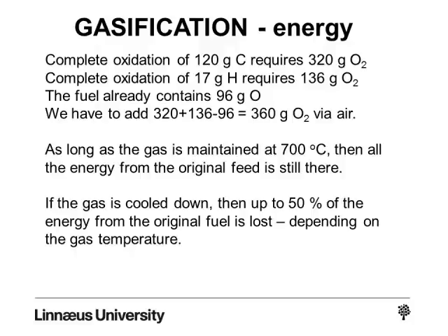But if the gas is cooled down, we lose from the gas the sensible energy. And if we cool down the gas to ambient temperature, then we have lost 50% of the energy content in the product gas. And only those 50% of the energy content that are there because of chemically active compounds, carbon monoxide, hydrogen gas and methane gas, only that energy remains.